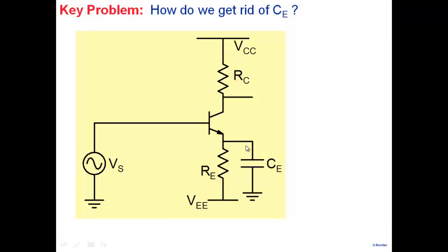And under DC condition, what are you looking for? High impedance, or something which will not disturb the current here. Biasing, which will not disturb your biasing, right? That's what you're looking for. So you're looking for an element which, under small signal conditions, is a very low impedance, and it does not absorb the DC part here.